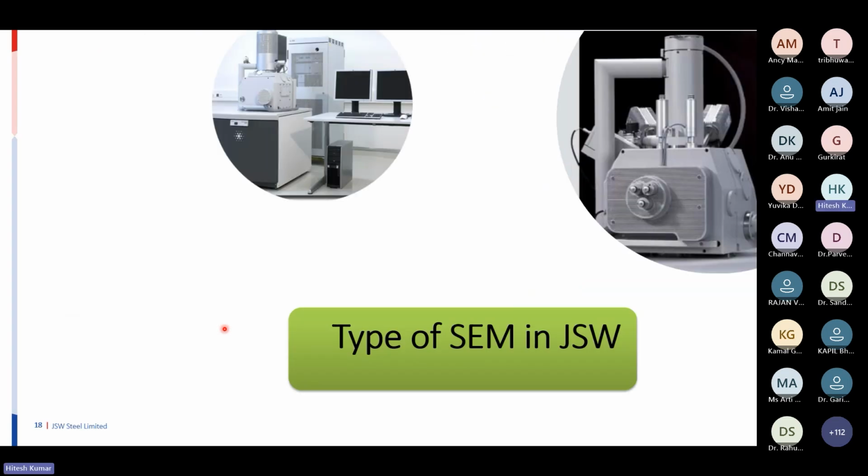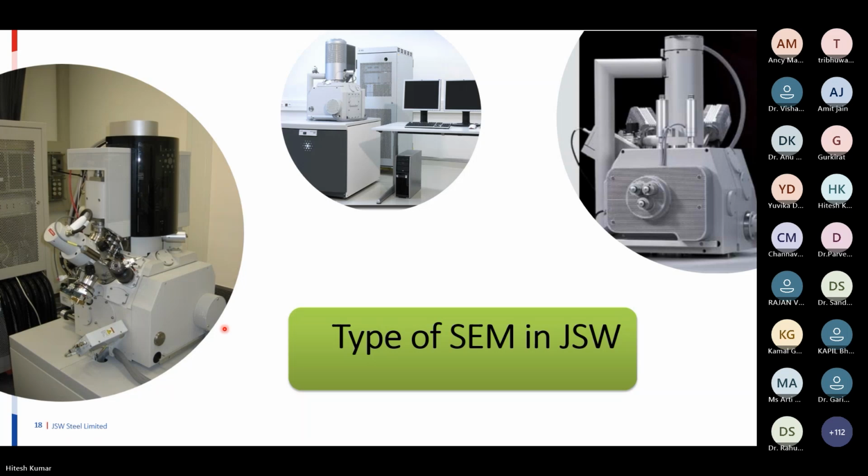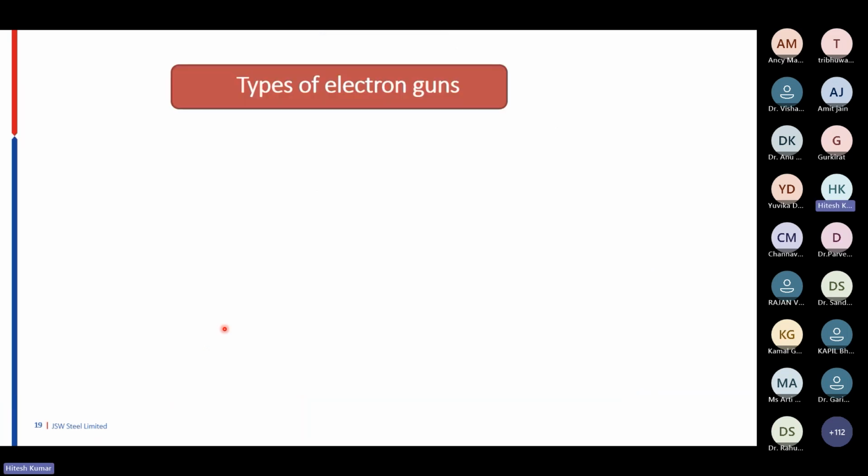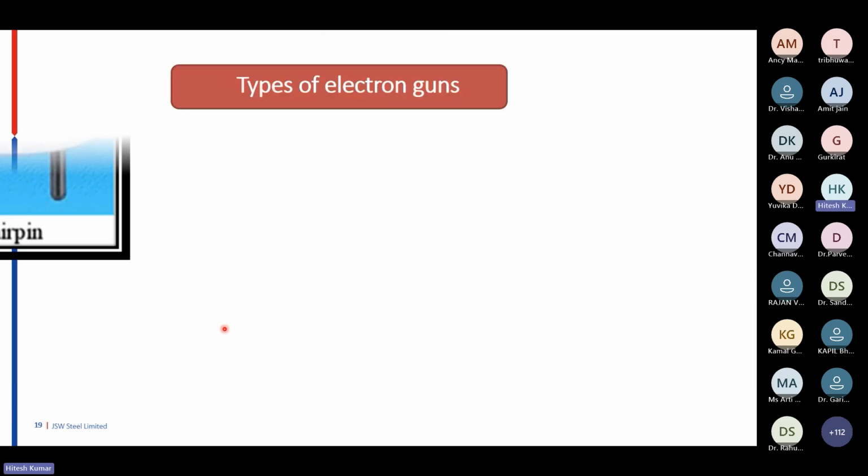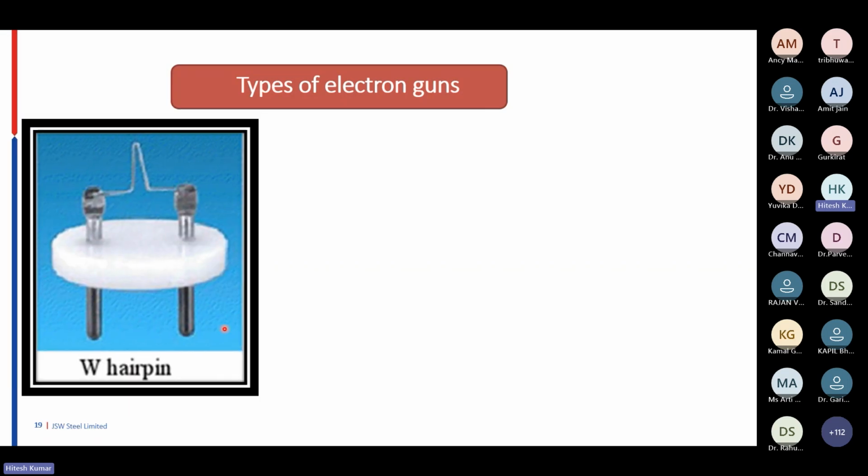So now these are the different microscopes which we have here. If we talk about different electron guns, which I asked about earlier, the first one is the tungsten filament. The tungsten filament is basically used in old microscopes. It usually has a working life of 100 to 200 hours, depending on how well you are using it, which aperture size you are using, and what type of samples you are using. So that is basically the tungsten filament.